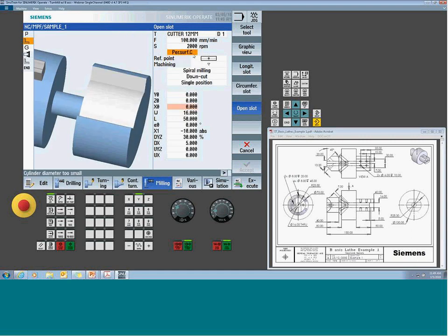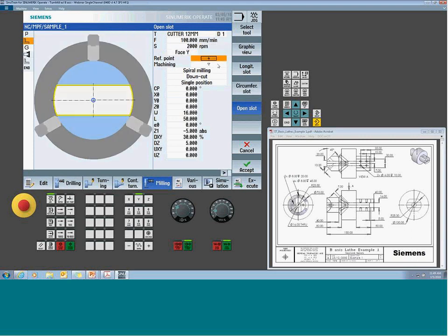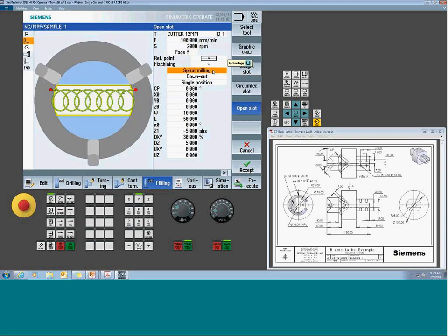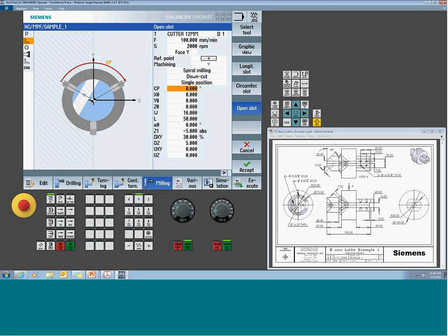All right, am I working on the outside surface? I'm on face, and we'll do its calculations from that. The rest is just going to be standard. Where's the center? What's my technology or my tool path strategy? Conventional mill, one slot, multiple. Now, the orientation position becomes important, how I can clock where the slot is. So I have this slot be at C0, basically. So it's going to machine a slot straight up and down.